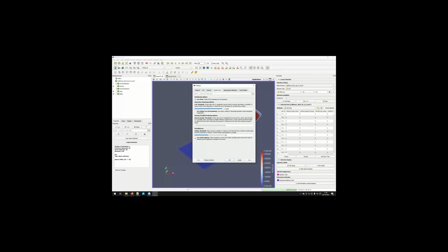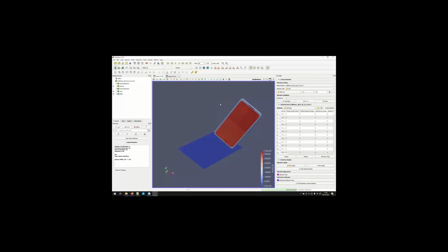You know, when you open very large data and move the data with the mouse, for instance, there is an automatic decimation. So fewer triangles are rendered, and as soon as you release the mouse, the full model is rendered. So there are lots of tricks in ParaView that you can activate or deactivate if you don't want them. And I haven't spoken about client-server architecture, which is a bit out of the scope of this webinar, but in client-server architecture, all the rendering happens on the server, and you stream only images. In this case, we also have lots of strategies to compress images, to stream as little data as possible to make the experience as smooth as possible for the user.